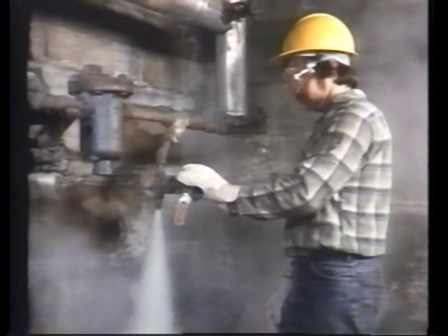Finally, make sure the trap strainer has been blown down. Usually opening the strainer blowdown valve 1 full turn and then closing it will provide enough flow to clean out the strainer. Now, as you make these checks, keep in mind that ideal conditions are rarely found, so it's a good idea to check the operating history of the trap.